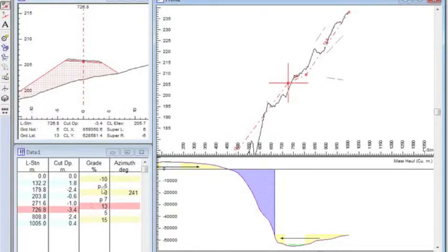The grade break is quite large, 7 to 13. Well, that's a curve. 13 to 5 to 15. So there's big grade breaks in there. We probably should put some curves in. So I'll do that.